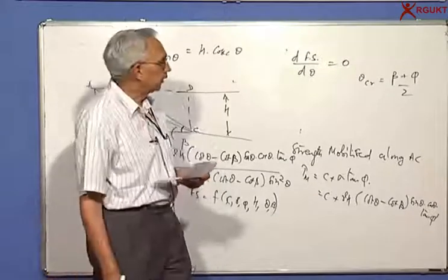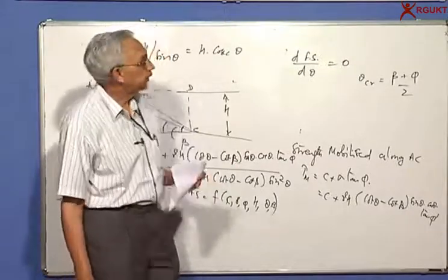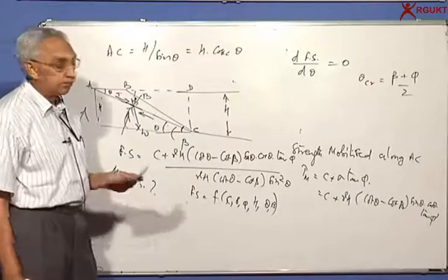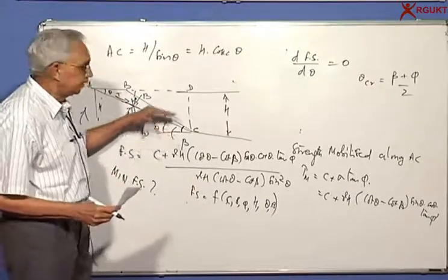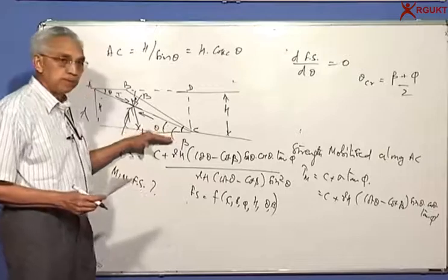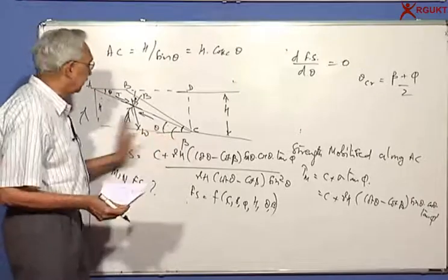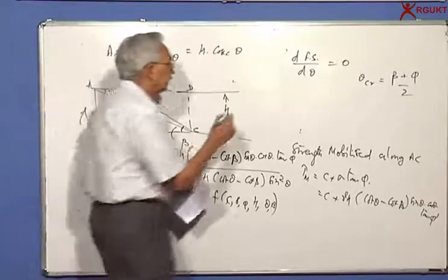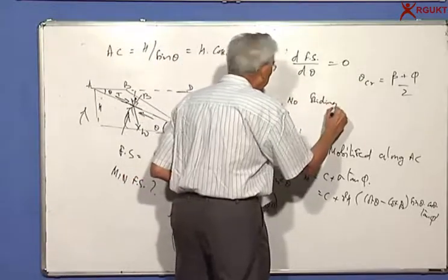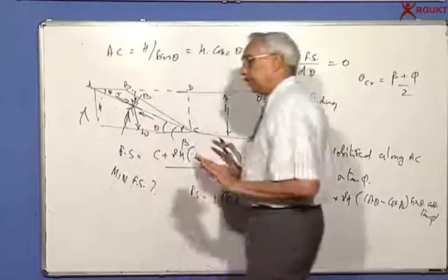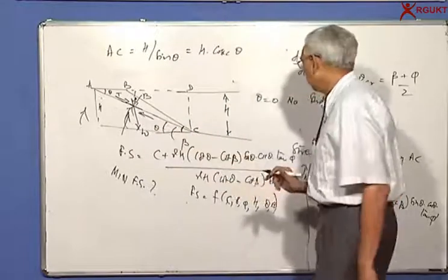That's as simple as that, particularly for the very little friction angle, etc. So you find that as you increase theta, when theta is 0, there is infinite factor of safety because there is no sliding force. Theta is equal to 0, no sliding, because the plane is horizontal, so there is no soil which is pushing.